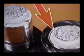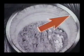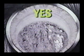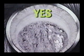Severe stress raisers include heat treat cracks, inadequate fillet radii, gouges, dents, and shrinkage voids. The design drawing for this part specifies a fillet with a radius of 120 thousandths. The actual radius measured on the part, however, is 36 thousandths. Is this an abnormal stress raiser? Did you answer yes? If so, you're right. The smaller radius results in an abrupt contour change, which increases the stress multiplication.